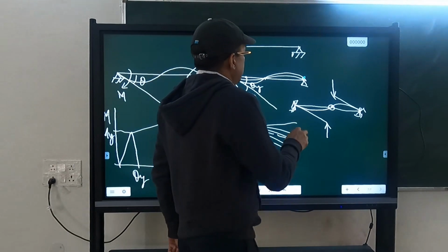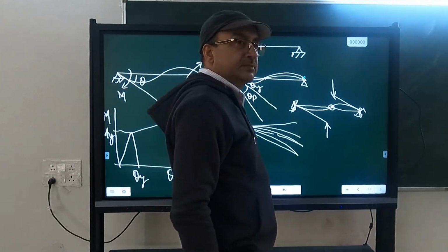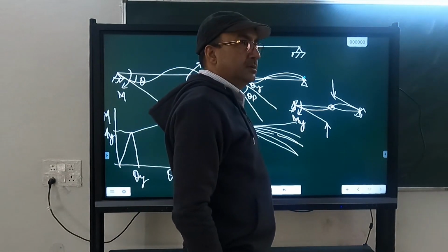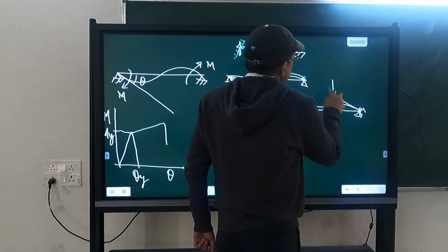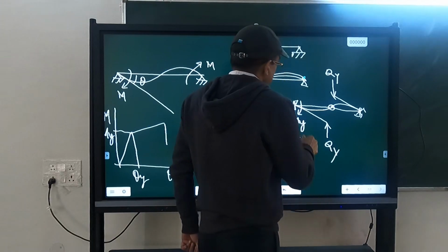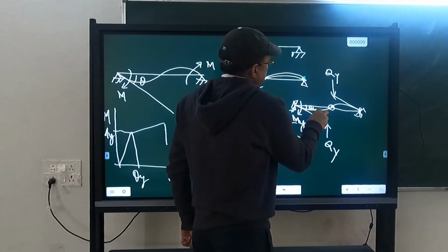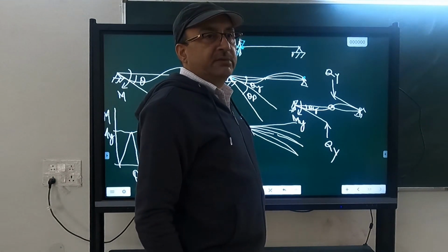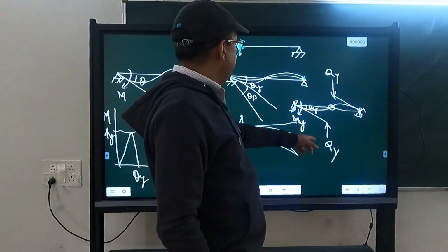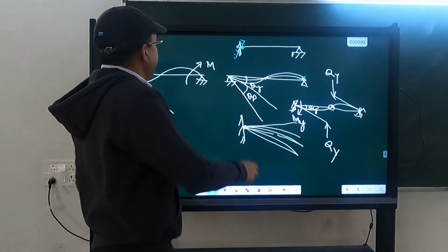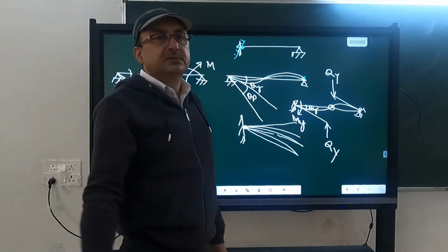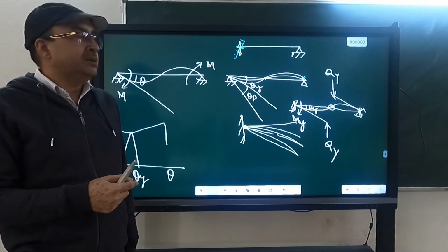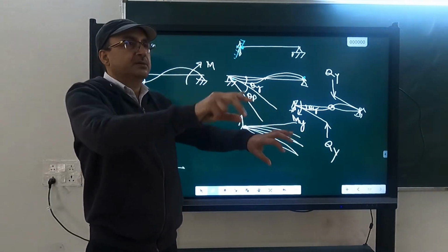So can you calculate it in this case? How much moment will be required here at the yield point? Let us say this is Qy. If this angle is theta y, you know the relationship between My and theta y? You can calculate theta y in terms of My, same as you have done in the case of a cantilever. So till the yield point, these will be treated as two cantilevers connected by a pin at the point of contraflexion at the midspan, and after that the rotation is free. Theta will go on increasing.